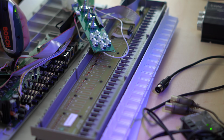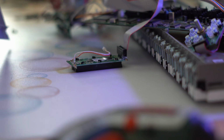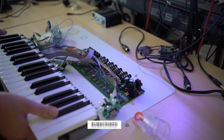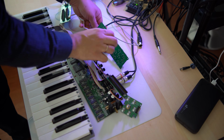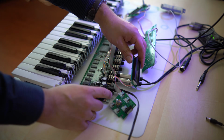Now, remove the 8 screws holding the mainboard and the 3 mod wheel LEDs in place, and then you can also put away the bottom plate, leaving us just the circuitry. Let's lovingly rearrange the synth innards on the table. If you take care so the PCBs don't touch each other, I think it's relatively safe to connect the audio, MIDI and the power brick and turn this thing on.